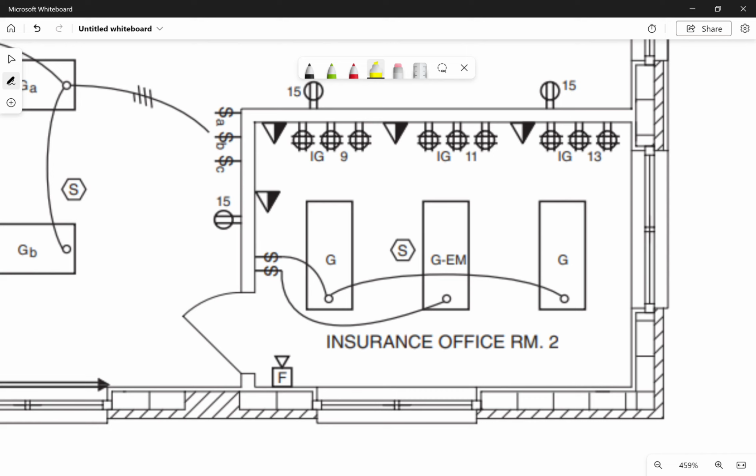As you see in our insurance office, I'm not sure if they are planning on running a Bitcoin operation or what they've got going on here, but they have 9 quad receptacles in a room that appears to be not much larger than a 10 by 12 room. And so it's going to require more volt amps of coverage than this room requires, and we want to count that when we're adding those things up. And those are all things that we'll talk about in class this following week.